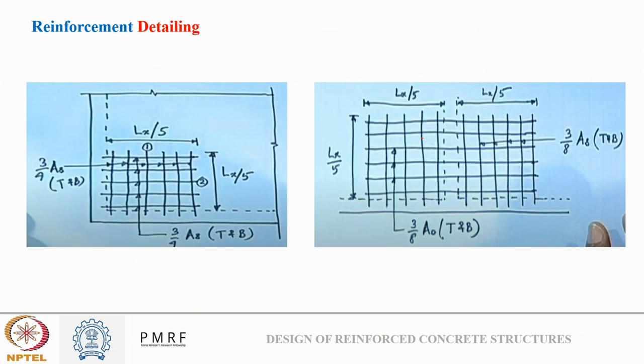Okay. Now, when we talk about restraint support, there are torsional stresses that can be generated near the supports as a result of restrainment. So for this, what the code says is we need to provide steel mesh. So you can see these are steel meshes. Okay, now how to design for it?